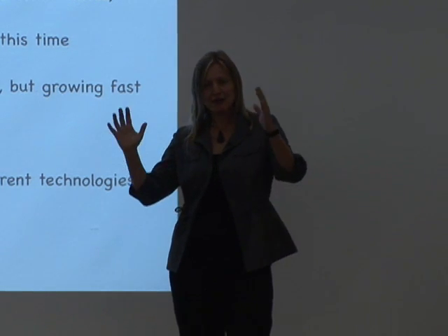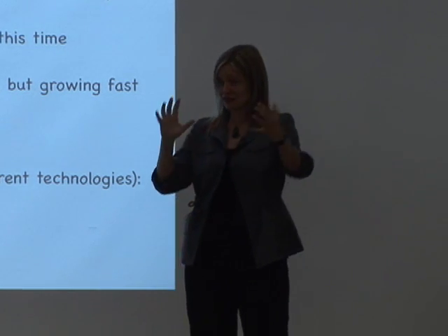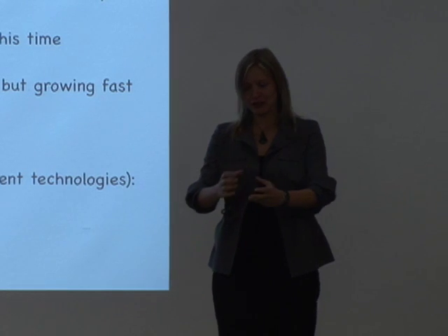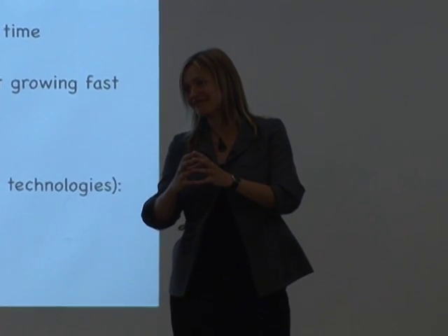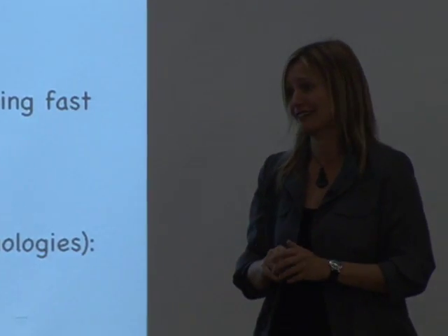So you can either take a wind turbine and try to make it suitable for water, or scale it down and beef it up. Or you can take a propeller design and scale it up and slow it down. Both of those cases require a complete blade redesign. But the largest cargo ships in the world have like, I don't know, 10-meter blades and like 100 RPMs or something. Yeah, and so there are people there.